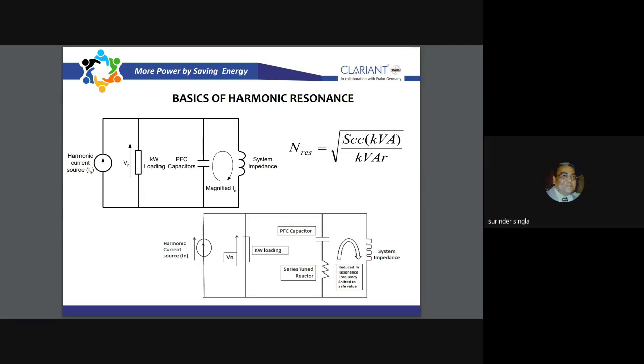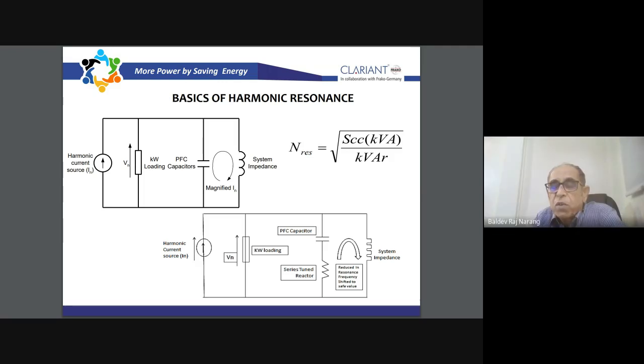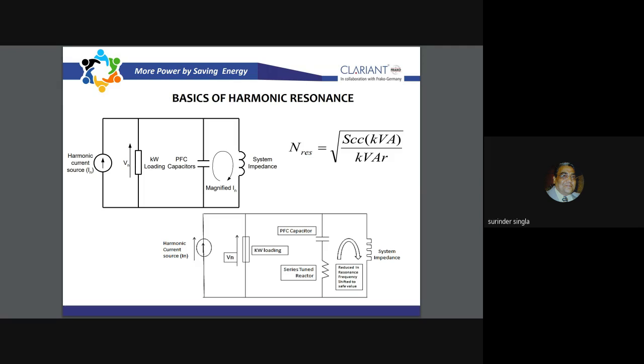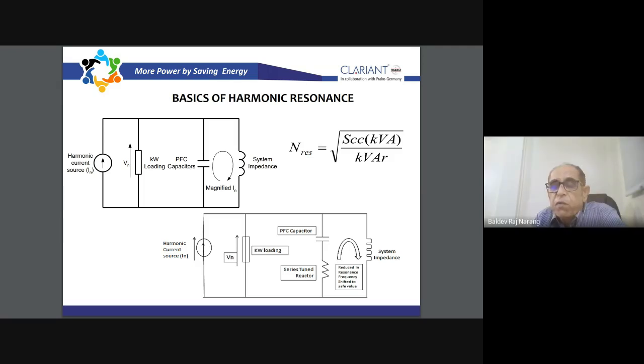You mean for fifth and seventh harmonics, we have the same design? It is the same design. We don't have two different filters. We have the same capacity of the component? Yes, same filter. Whatever we do for the fifth, it is mainly taking care of the fifth harmonic and all higher order harmonics to some extent. Maximum is fifth. It gives low impedance to all the higher order harmonics, not only fifth. So all are reduced to some extent. But we don't design two different filters.